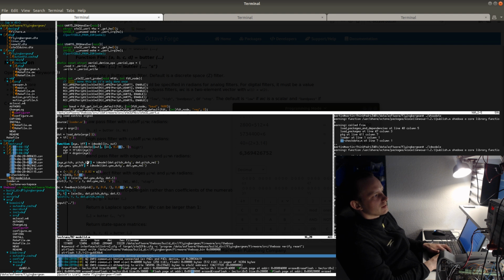What I get here is the system for the pitch and the yaw. But it's also possible to just iteratively identify the first order system, which is what I do here. This is basically a transfer function approximation, which is very easy to do when you have the measured data. You could just do it like this. Let's see.